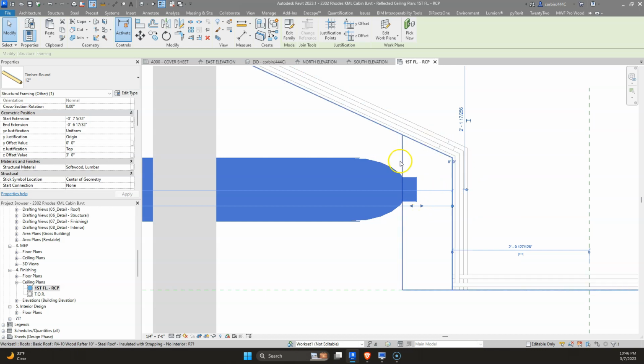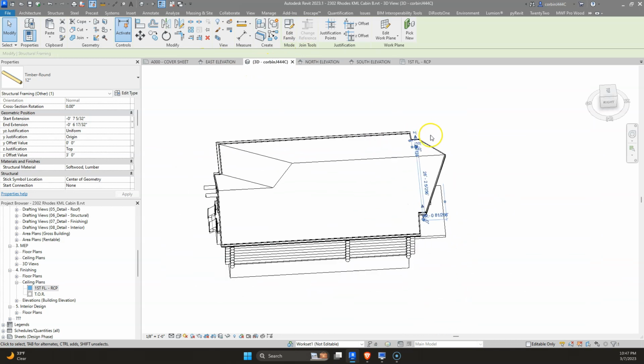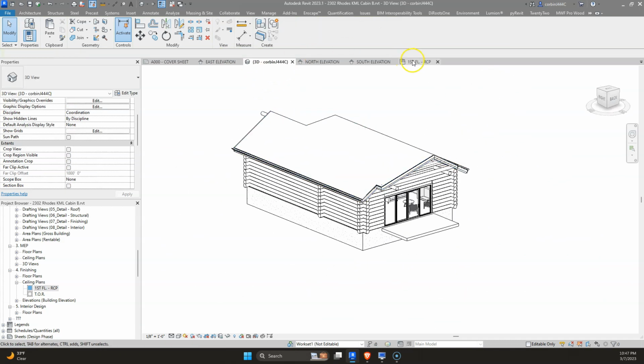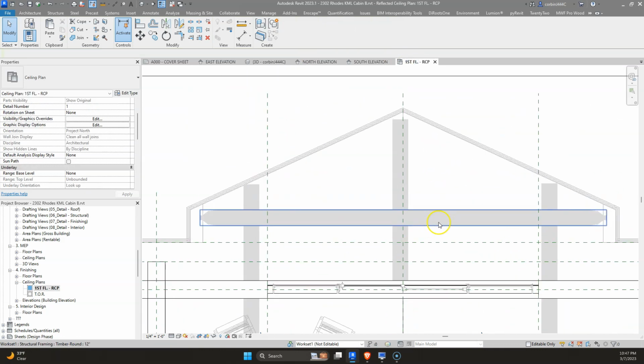My usual rule of thumb is, you generally always want to move this dot unless you're making a change under 6 inches. And what I mean by a change, you're altering the end condition of that log or that beam. But I usually like to move this dot before I move these arrows. So just kind of food for thought there. So let's just double check. Our log is not sticking out. Perfect.